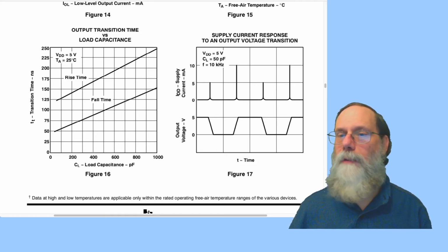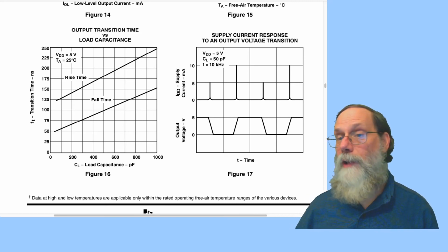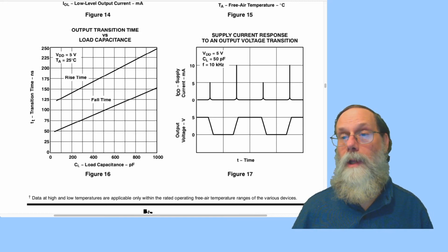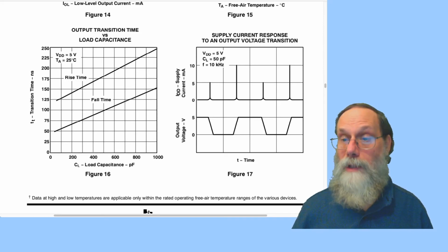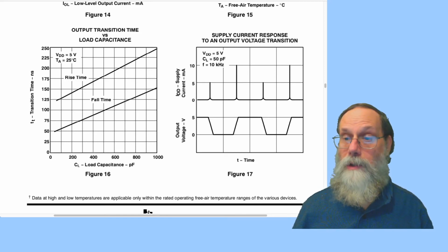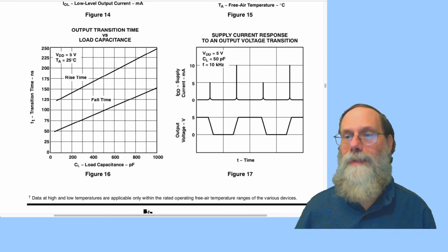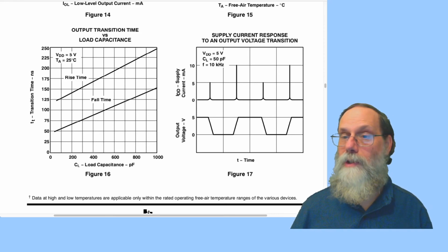How fast we can drive it is going to depend on how much this rise and fall time changes with the capacitance. If it turns out the comparator can't drive the field effect transistor fast enough, then we can put in a CMOS inverter, which has slightly larger transistors than are inside the comparator, and so lower on resistances, and so is able to drive a large capacitive load quicker.